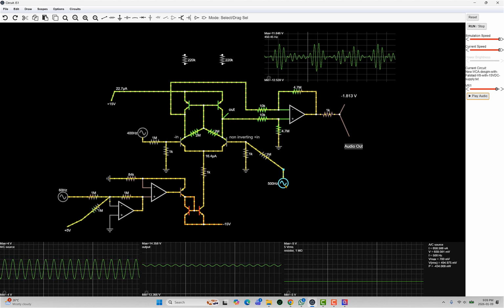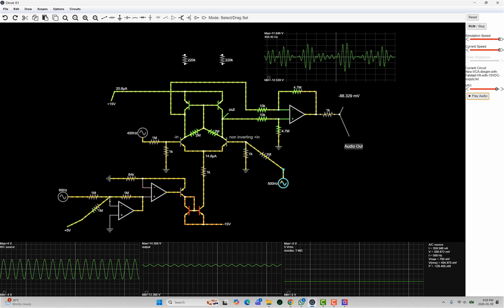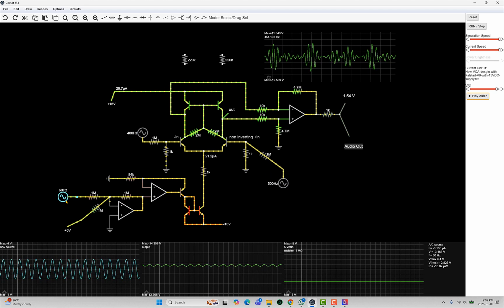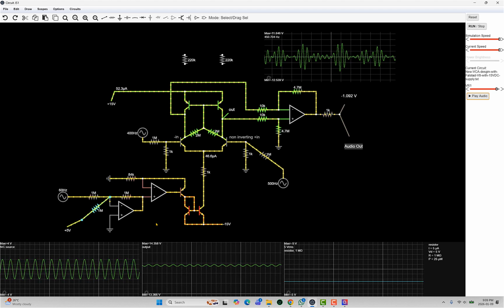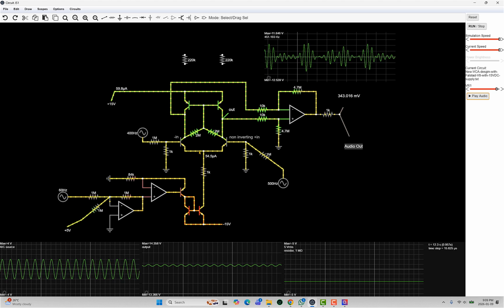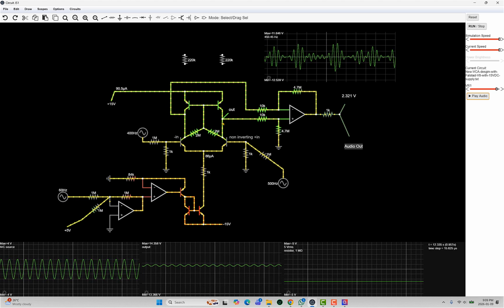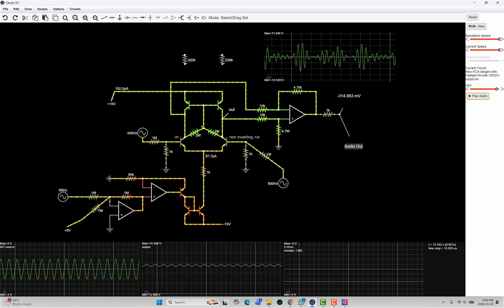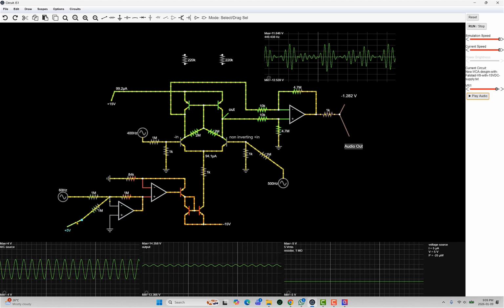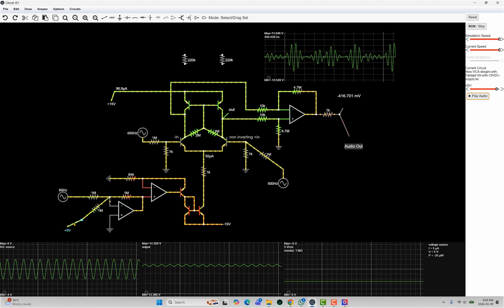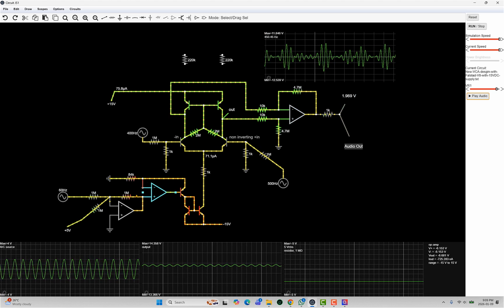Kind of neat. And how I did that was combining 400 hertz with 500 hertz, and I'm modulating it. This signal here controls the amplitude of this amplifier. So the amplitude is going up and down, or in other words, the gain of the amplifier is going up and down at a 60 hertz rate. And I can vary all these. And I found out I needed a DC offset mixed with the 60 hertz so it properly works.